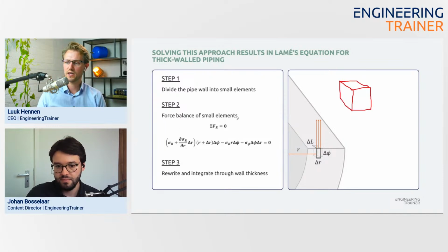What this equation means is that for each direction, say this is the longitudinal direction, you write down what the force on this side of the element would be, and what the force on this side would be, and you say that those added together are 0, and you do that for each direction. So you end up with 3 equations, which is the same as this equation once you write it down for each of these areas.